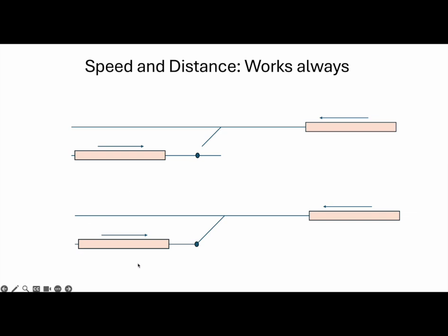So, for example, if they are very slow, of course they can get near. And if they are very fast, of course they cannot get near. These are parameters you can set up as configuration parameters. So in the end, for a movement, there's no need to set up a static flank protection or something. All you need to check in terms of safety is what is the reachable path for a movement and what is the distance on that. So for each situation, each topology, each status of the points, you can always use this simple basic rule to check.